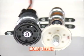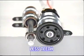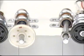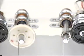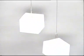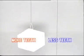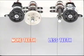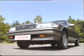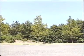The shafts of the two models used to wind up the threads holding the weights differ. This difference corresponds to that of the number of gear teeth of the transmission. The one with less teeth does not show any significant work. On the other hand, the one with more teeth lifts up the weight slowly due to the bigger torque it can generate. This is the same as the combination of gears automobiles use for starting or driving uphill.